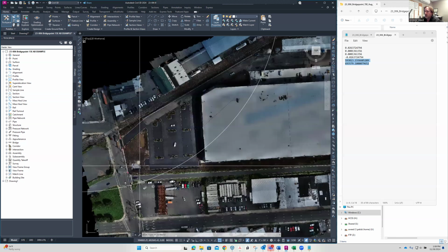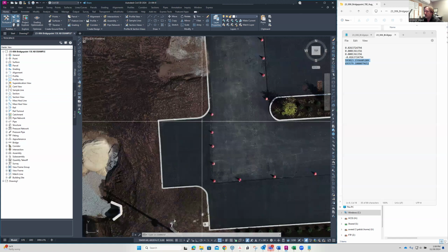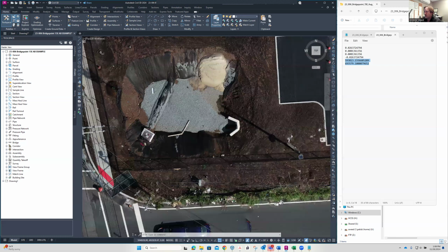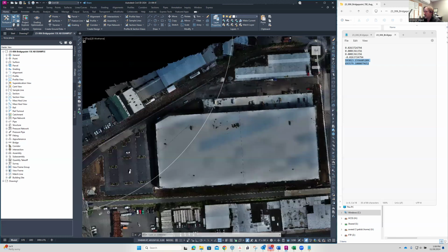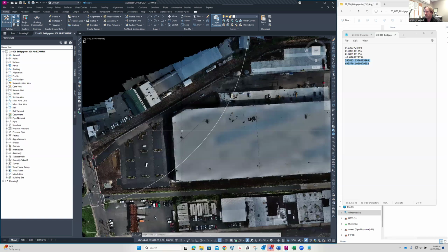But for as-built purposes, the orthophoto, we use it to locate the curb lines, which you can see very clearly, the storm structures, another storm structure. That's actually an outlet structure. This is the warehouse building itself. This is concrete pavement. And we actually use this. We do survey a lot of data on the ground as well, but a lot of the actual two-dimensional planimetric drafting we end up doing directly from the orthophoto.